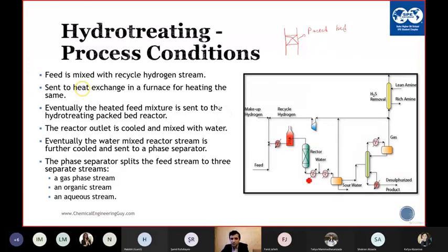And this is a one reactor. It has one packed bed reactor. So for CCR and FCC, we had the regeneration of the catalyst, and we had the continuous catalyst regeneration for each of the process. But here we have one reactor without any regeneration. So this is the difference between the reactor in this process and other processes. Lifetime can be up to 5 years.